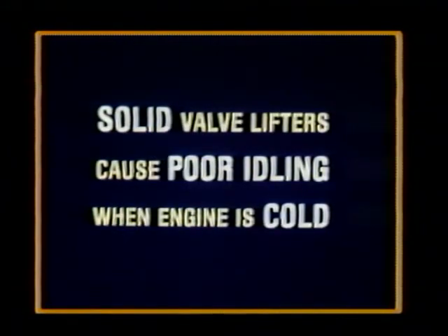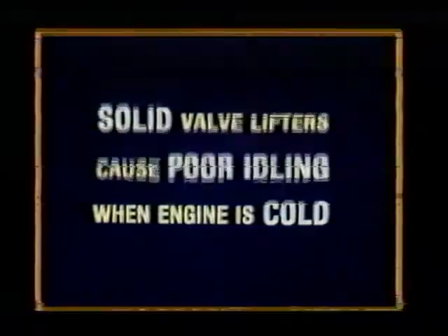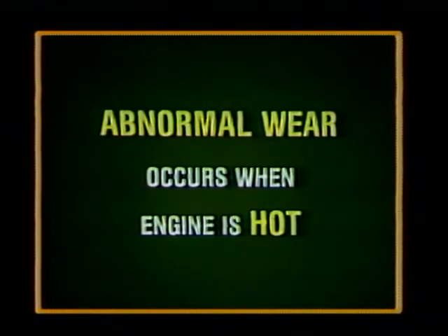As a result, valves using solid valve lifters are timed to open properly when the engine is hot. This means the engine has very low volumetric efficiency when it is cold, usually causing rough idle. Another problem is abnormal wear of the components in the valve train due to excessive clearance at operating temperature.